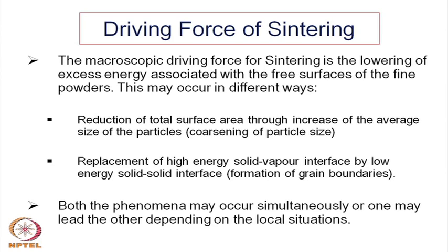It is also an interface, it is also associated with some kind of surface energy, because the surface is very much there. But the surface energy for the solid solid interface is lower than the solid vapor interface, and that is also the driving force. There is always a tendency to lower the overall free energy or the overall surface energy term, and that surface energy term can be reduced by replacing the solid vapor interfaces with solid solid interfaces. So, that is another driving force for the sintering.